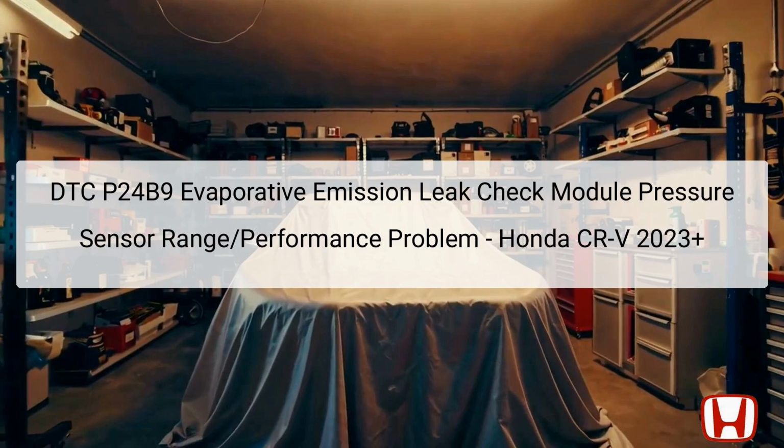Located in the EVAP system, the ELCM plays an important role in assessing the system's integrity by monitoring pressure changes. A faulty ELCM sensor can disrupt the vehicle's emissions control strategy, potentially leading to increased pollutant emissions. Understanding and addressing DTC P24B9 is essential for maintaining compliance with environmental regulations and ensuring optimal vehicle performance.